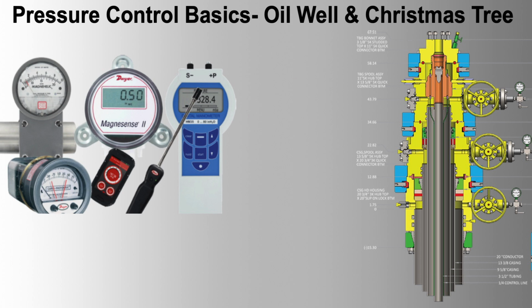2. Material selection for sour service. Corrosion resistance. For sour service, H2S environments, materials must resist sulfide stress cracking and corrosion. Common materials include Inconel, Monel, Hastelloy, and duplex stainless steel. NACE MR0175/ISO 15156 compliance. Ensure materials comply with these standards for use in H2S containing environments.